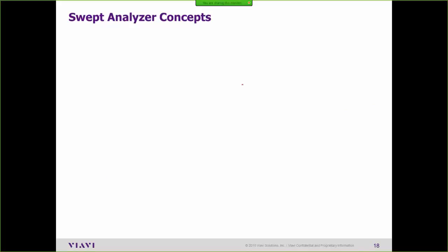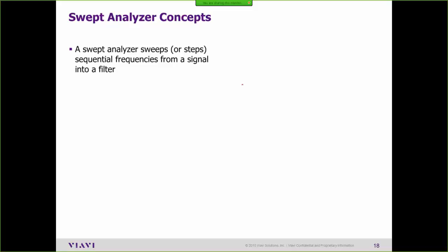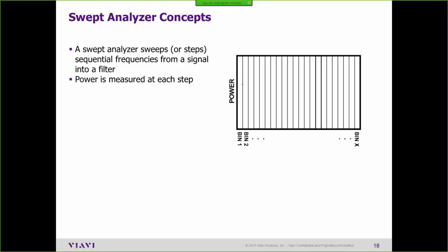All the measurements that you see on the screen are related to a bandwidth. The bandwidth on a spectrum analyzer is called RBW. That's the key measurement that determines how much power the analyzer sees, and what positions the line on the screen at a particular level is how wide that bin is.